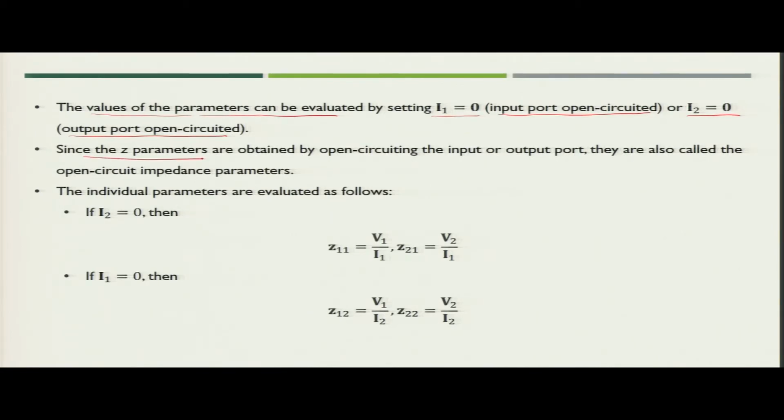Since these Z parameters are obtained by open circuiting either the input or output ports, they are also called open circuit impedance parameters.